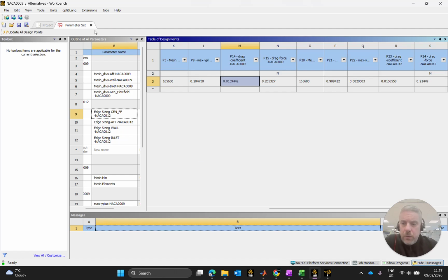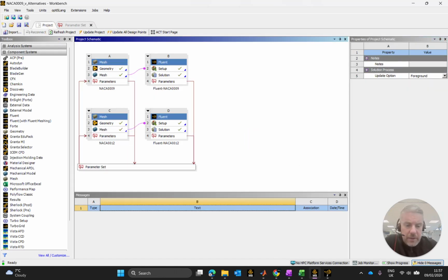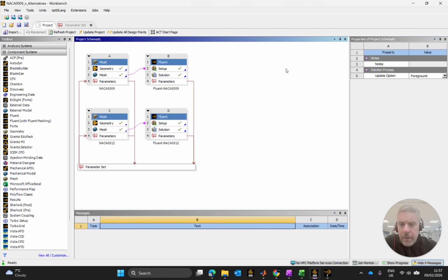So what I'll do nice and quickly here for ourselves is shrink this down. I'm going to repeat the whole process again, and I'm going to bring in a new airfoil. The airfoil I'm going to use is going to be one of the Selig airfoils. It is going to have a 12% thickness relative to chord length dimension. So I'm going to put this on pause just to bring it in. I'm going to do a lot of the groundwork here, just copying and pasting these in. If there's anything that's come up that has been strange, I'll certainly come back and I'll mention it.